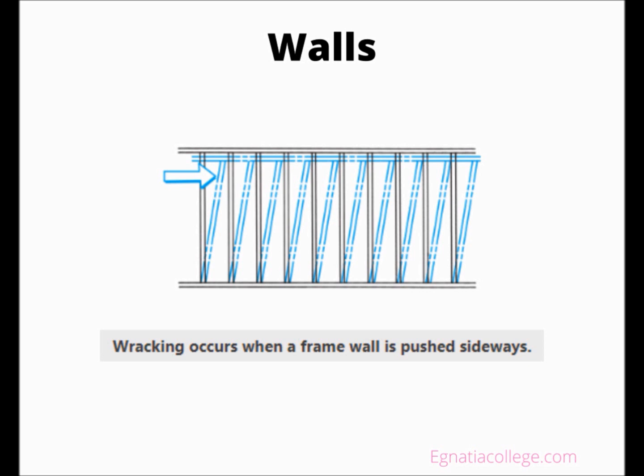Notice the garage door openings on the bottom floor. Since the shear panels cannot continue across those openings, the narrow wall on one side of the opening is paneled on each side and has heavy hold-downs tying it to the foundation. There is also shear transferred from floor 2 to the first-story wall.